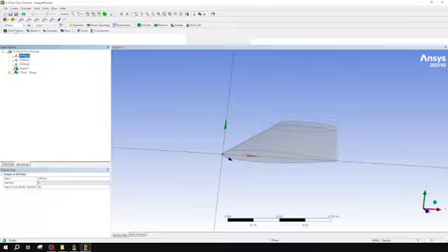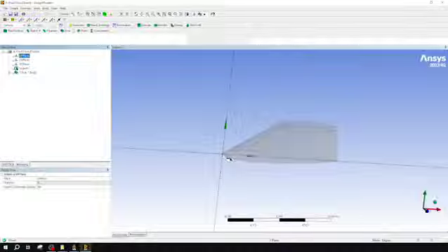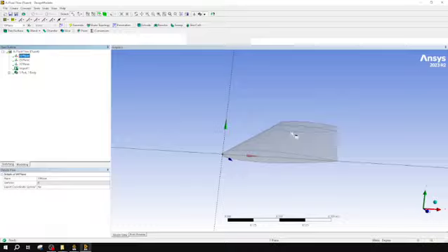So I'm going to select that plane. You'll see it brings up my axes. It always imports your object with, I believe, the origin of my SolidWorks file at the origin in this import. I can't guarantee that. I've always made my model like this, so I don't know if that origin is correct. You might need to play around with that yourself.